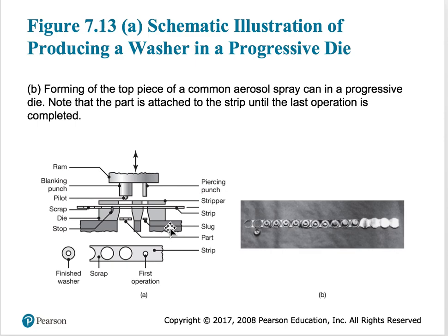Then you can also have what is called friction sawing, using a disc or blade. The other one that is very commonly used, especially for composites, is called water jet cutting or abrasive water jet cutting. Those are used both for metals as well as for non-metallic materials. Then the more common one nowadays is laser beam cutting.